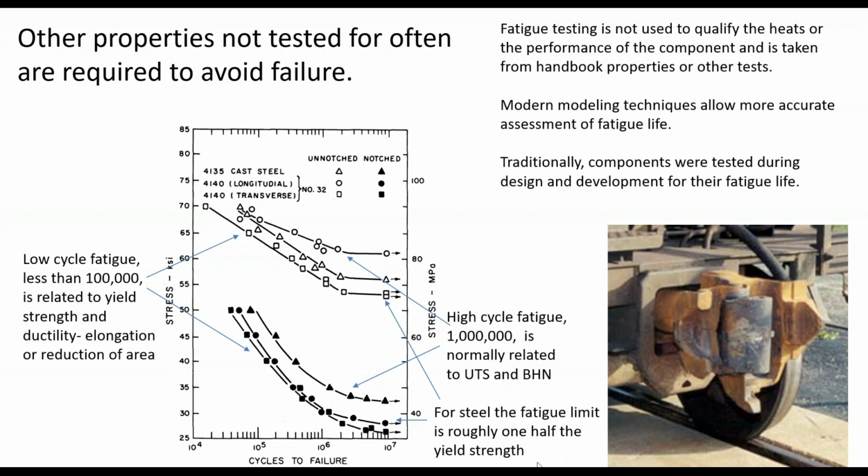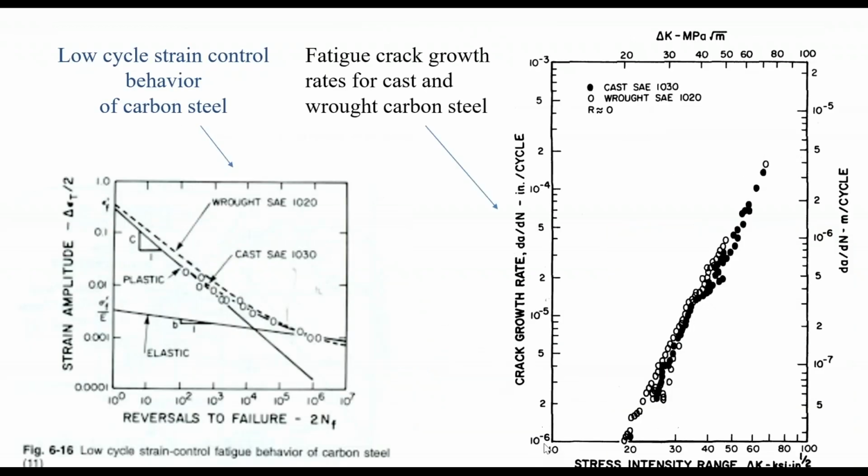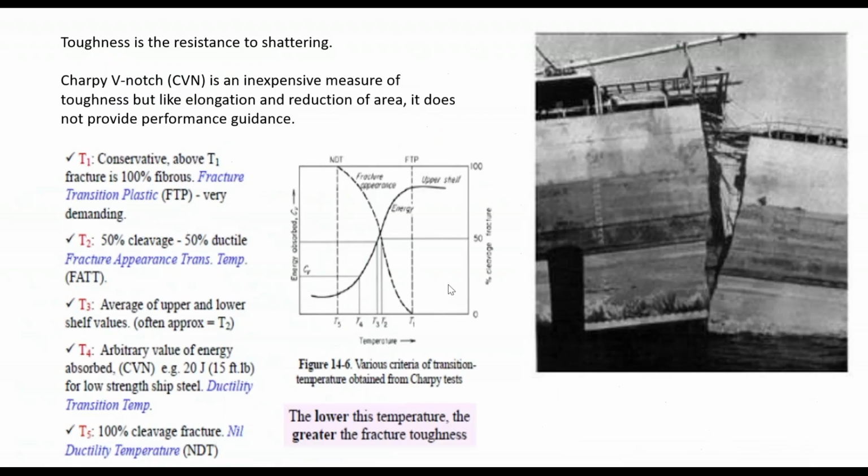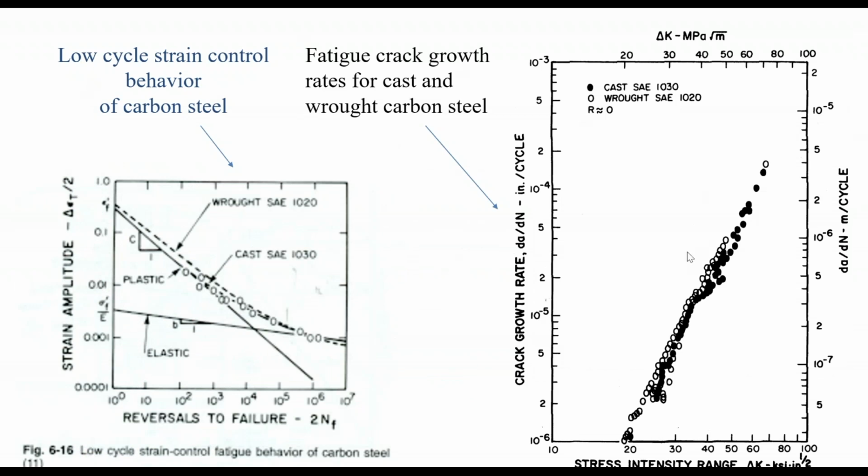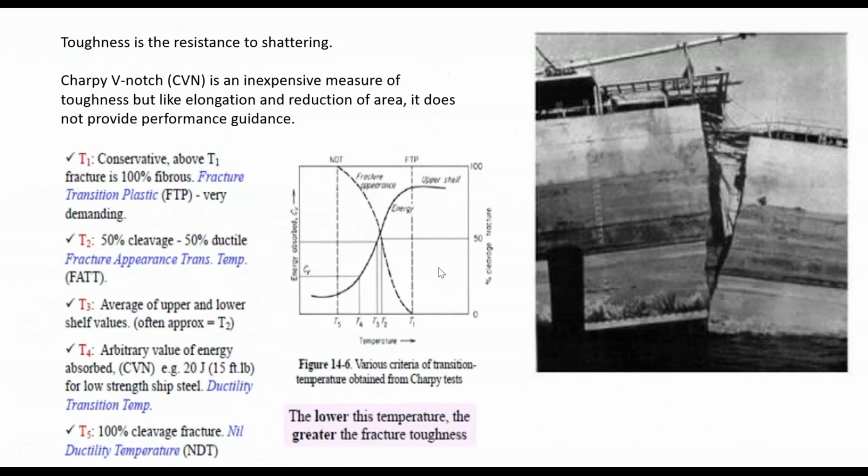Much of this problem goes away in terms of the geometry when you move from simple models to actual finite element analysis. Nowadays, we use things like plastic fatigue control to crack initiation or linear elastic fracture mechanics crack growth as a way of modeling. And so we have much better ways of handling fatigue today than we did traditionally. And these properties are not directly related to yield strength. So having higher yield strength wouldn't necessarily give me more safety.